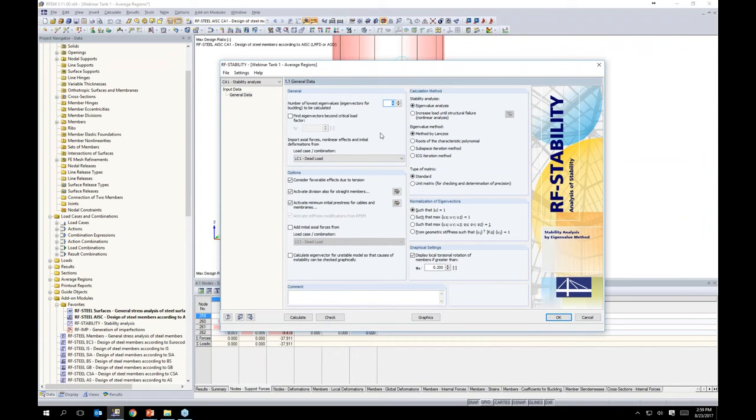This one looks a little bit different. Here is where we're going to run an eigenvalue analysis for our structure. And what this eigenvalue analysis is going to tell us is the various buckling mode shapes for our structure, whether that's related to the members or even the steel plates. So the default here is 4 eigenvectors to be solved for, but we can quickly change this to 10, for example.